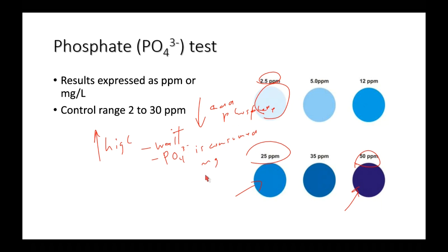Anytime magnesium or calcium gets into that boiler water, they are going to consume phosphate. So we just wait a little bit. Oh, we got 70 parts per million in the boiler. Well, let's wait a week, and then over that week period, we'll see that the phosphate residual drops.